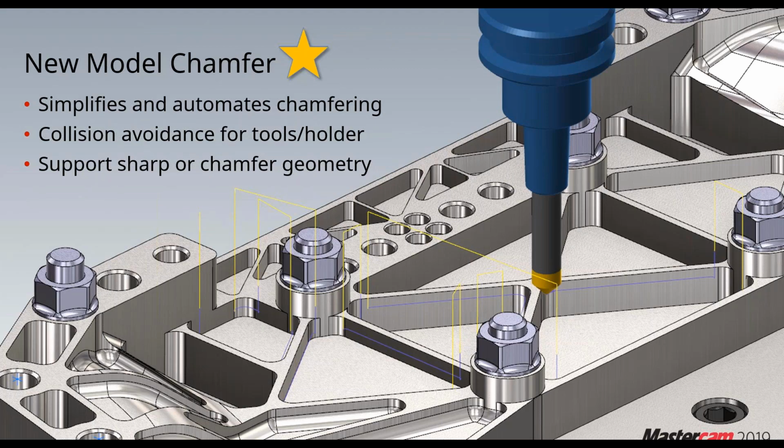So, 2018 added the additional chamfer support for models, and already, like a zero length chamfer, because the model might already have it on there. But this toolpath supports both of those. And the only thing you have to be mindful of here is it currently only works on flat chains.